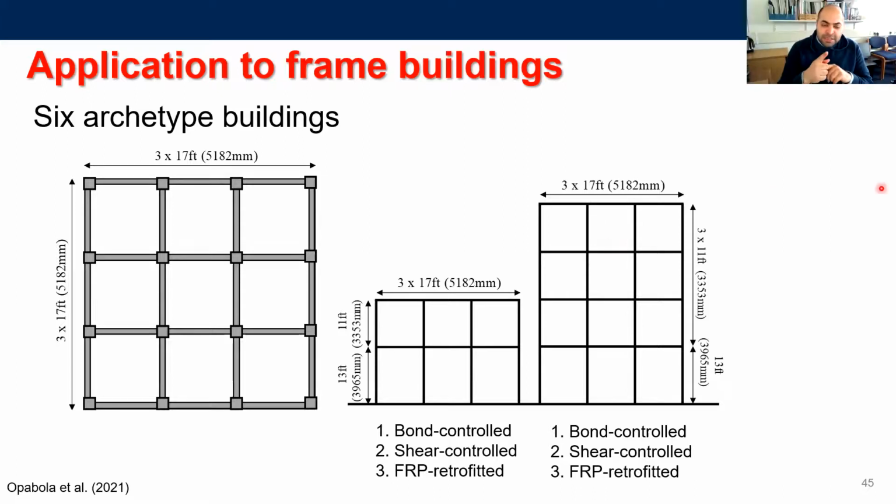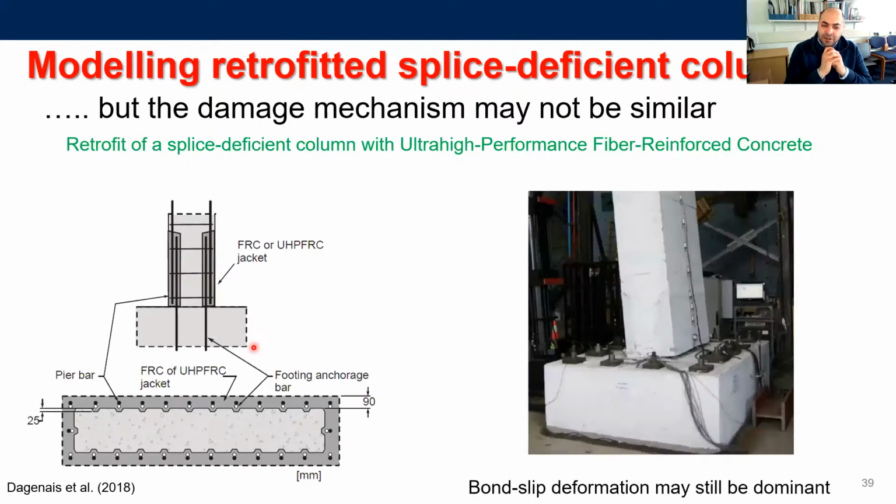Okay, and in the previous examples, you talked about FRC as well. Can you talk a little bit more about that, and what was the difference between that FRC and this FRP? So that was like a concrete jacketing combined with some fibers? Yes. So here you're having fibers, I think they used some 10mm fibers, which increase the bond properties. So it has a higher concrete bond behavior compared to normal concrete. What they did was use a jackhammer to scrape out all the concrete around the splice region, and then they filled it up with this high performance fiber reinforced concrete, which improves the bond behavior.